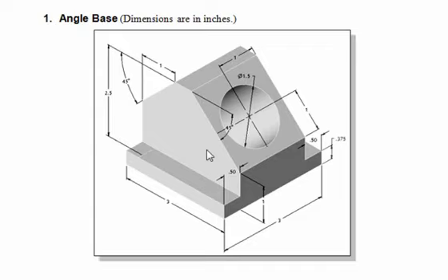One of the golden rules in engineering graphics is that dimensions must be placed on views that show true size and shape of the feature. For this particular design, we will start with the front view and then create an auxiliary view projected off the front view. So let's begin.